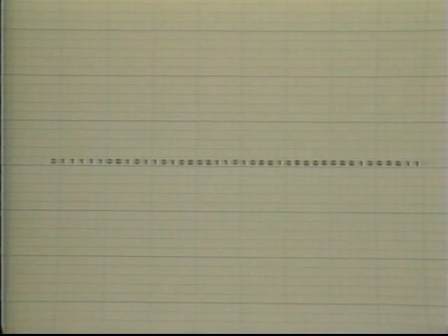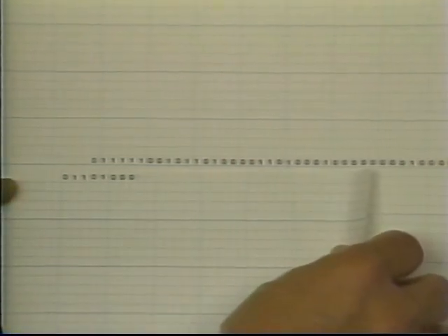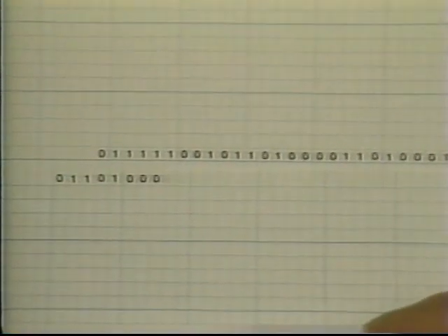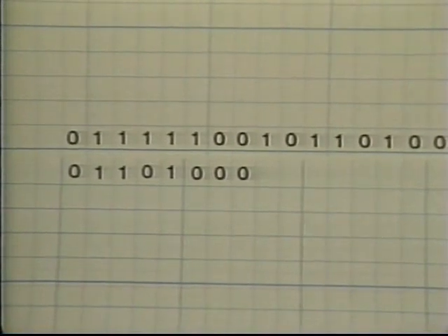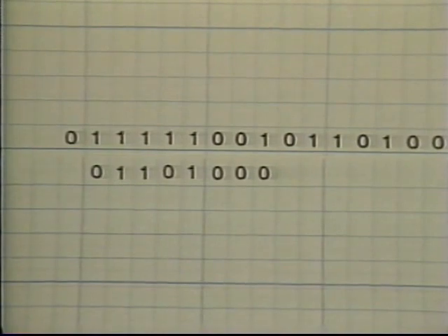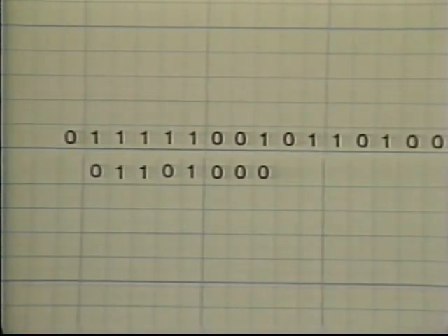This would represent a data stream that came down from the computer and did not have any start and stop bits in front of the information. Now the way the computer would pick it out would be through the use of a character called sync, which stands for synchronization. The computer knows what the sync character looks like, and here's our sync character on the line below. As the data is coming in, the computer counts off every 8 bits and compares it against the known sync character. If the first 8 bits doesn't look correct, the computer moves one time frame and tries again.